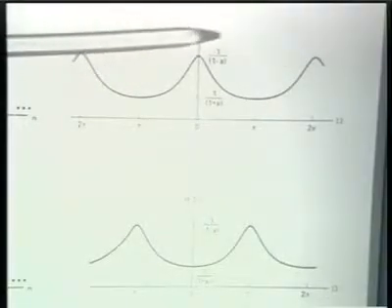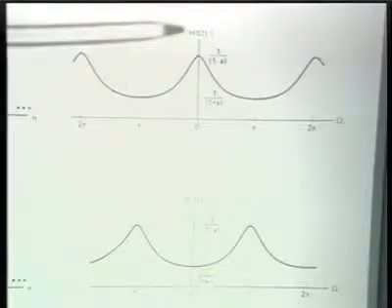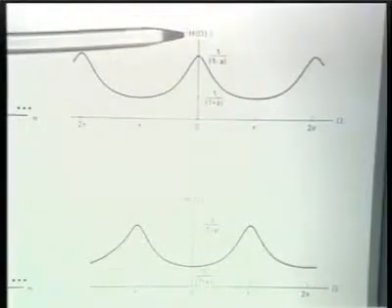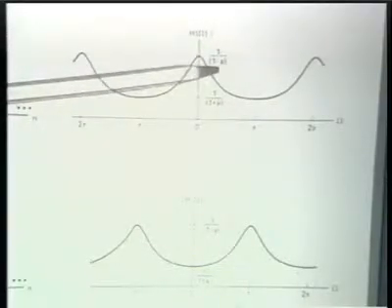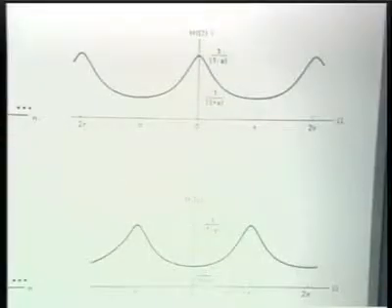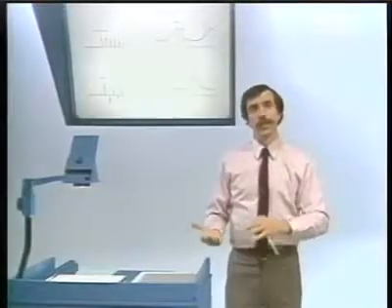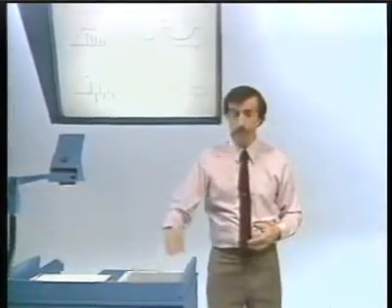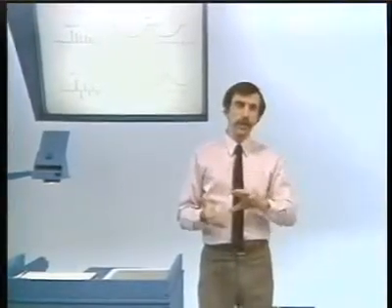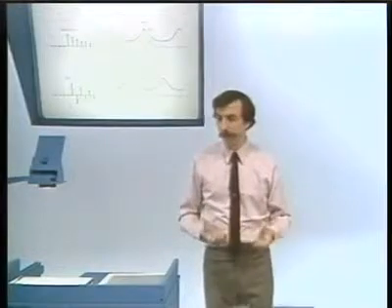As A is positive, we start to retain mostly low frequencies, and the larger A gets, but still less than 1, the more it attenuates high frequencies at the expense of low frequencies. So let's watch the filtering first with A positive, and we'll see it behave as a low-pass filter, and then with A negative, and we'll see the difference equation behaving as a high-pass filter.